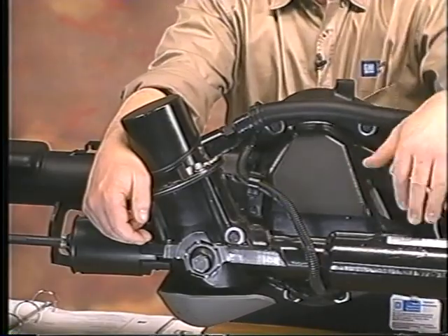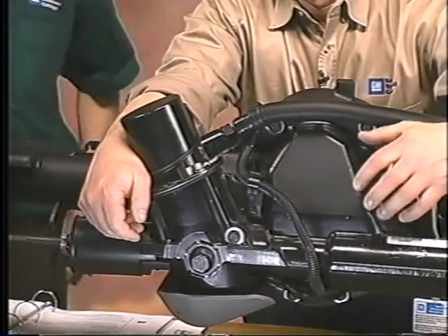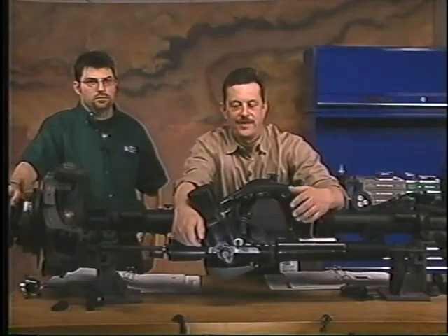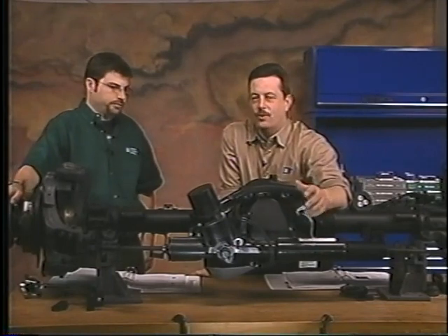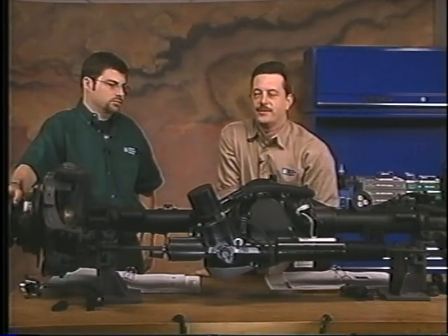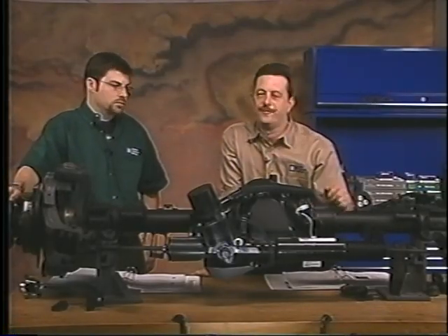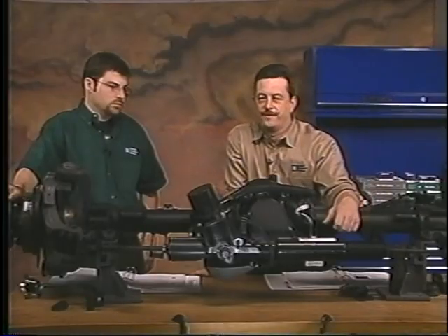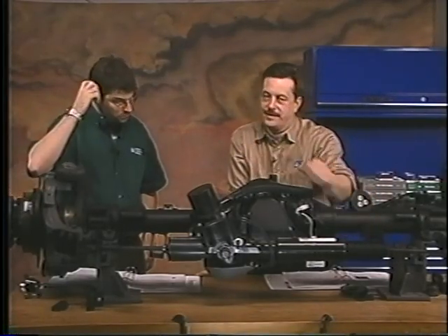Now, quickly about the axle itself. This is a Dana 9 3/4-inch axle, pretty heavy duty. It uses a synthetic fluid. Okay, synthetic fluid. Now, with that fluid, there's no change interval. Don't need it. Okay, no change interval. But if you had to drain fluid out of this thing, they do give us a drain plug down at the bottom. You're going to have to pull the shield off if it has one, and then pull that plug out and drain it out. Of course, we've got a typical fill plug on the side. So to drain that fluid out and fill it back up, you don't even have to take the cover off at all. So you don't have to deal with any of this.